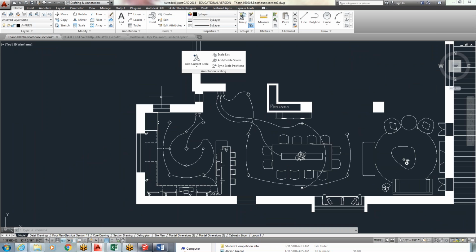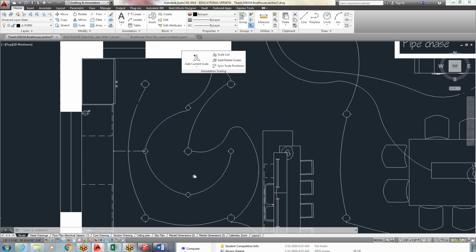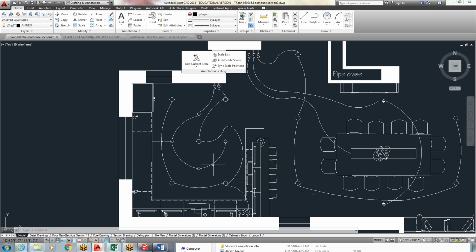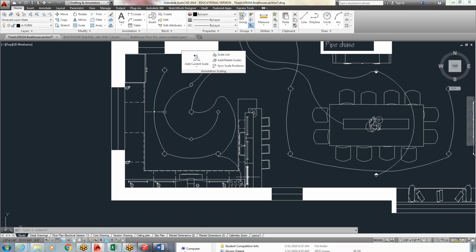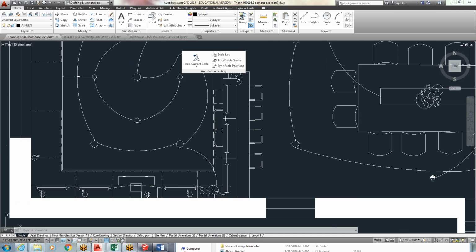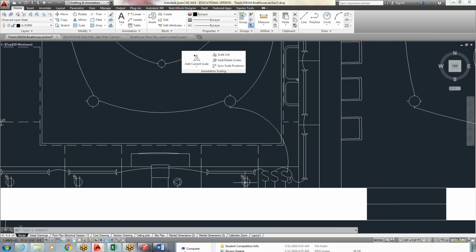In my layout for my kitchen, I'm showing some perimeter 6-inch cans. So this is a 6-inch can, this is a 6-inch, these 5 on the outside. And then I'm showing some 4-inch cans in the middle that would be dimmer, but just would help to radiate light through the center. And then I showed some under cabinetry task lighting, and then I had switching to each of those. So I also will expect some ground fault circuit interrupters, and they have to be,